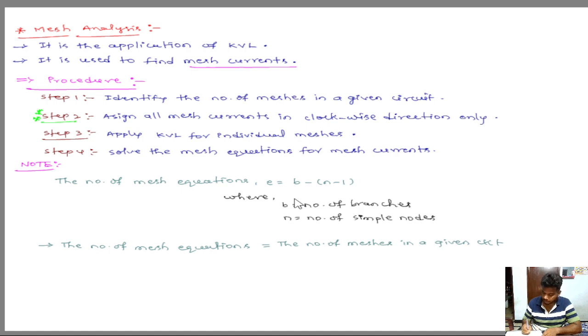Next, step 3, apply KVL for individual meshes. And step 4, solve the mesh equations for the mesh currents.